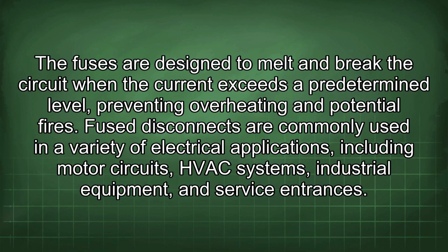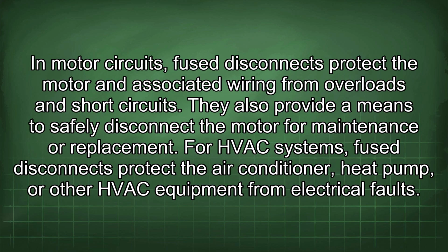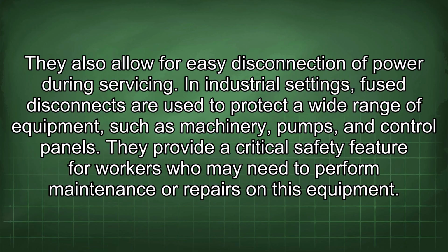and service entrances. In motor circuits, fuse disconnects protect the motor and associated wiring from overloads and short circuits. They also provide a means to safely disconnect the motor for maintenance or replacement. For HVAC systems, fuse disconnects protect the air conditioner, heat pump, or other HVAC equipment from electrical faults. They also allow for easy disconnection of power during servicing.